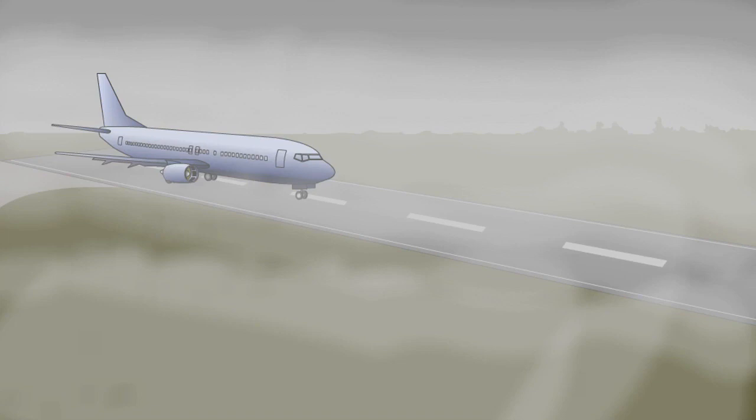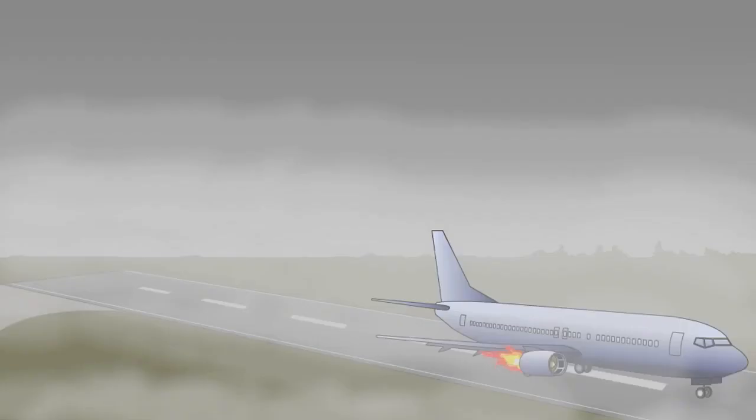Our MRJT will be Category C, that is, a target threshold speed, VAT, of 121 to 140 knots inclusive. We will also assume the aeroplane can meet its normal performance Class A requirements. That is, if the critical engine fails at any point during the takeoff roll, the takeoff run can either be abandoned within the distance remaining or continued to 1,500 feet above the airport while clearing obstacles by the required margin.